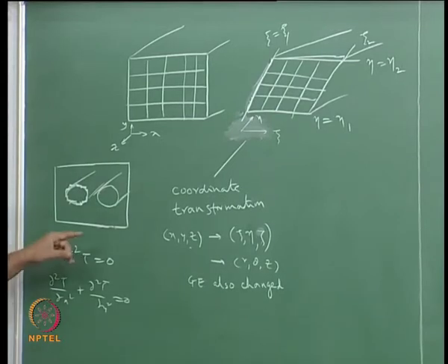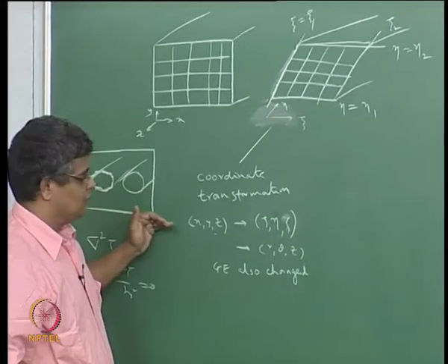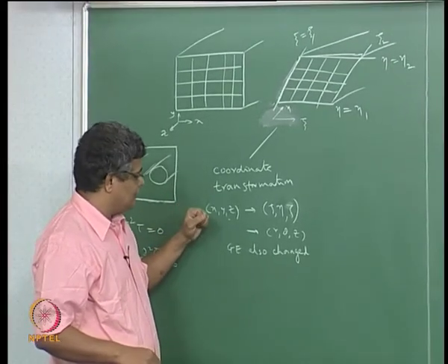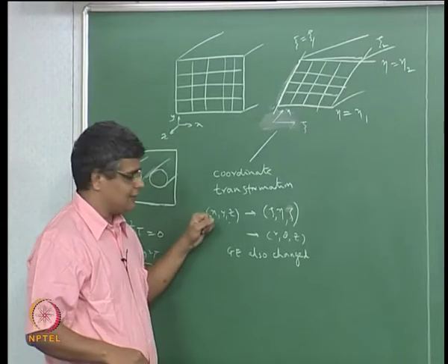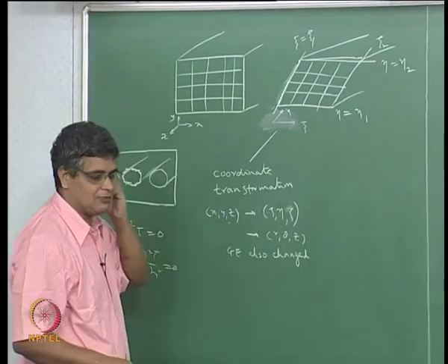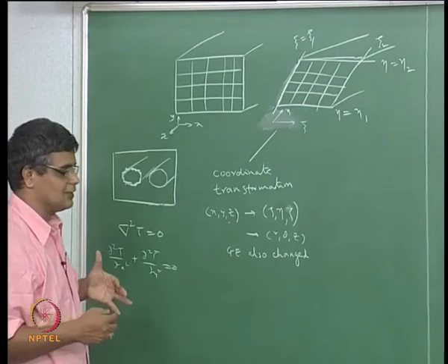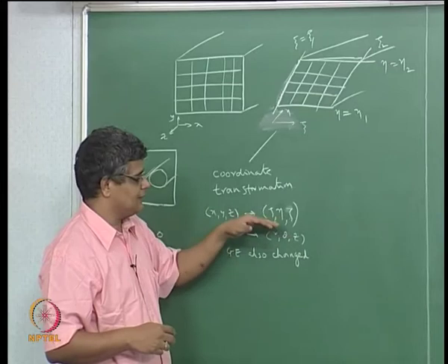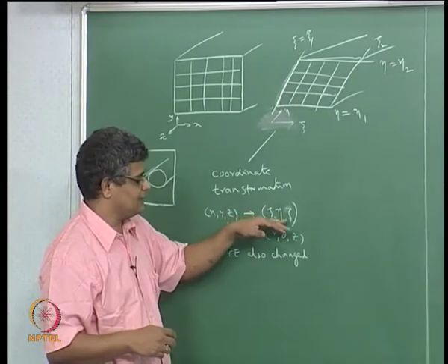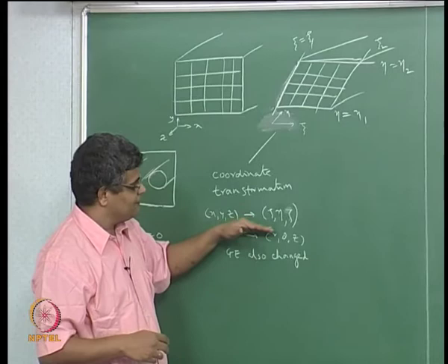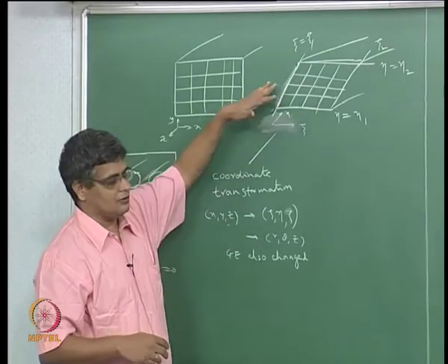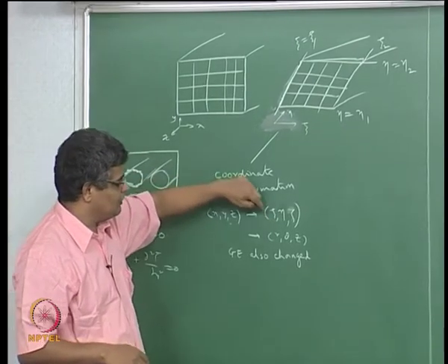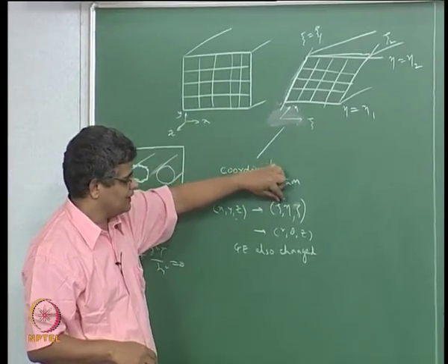So one approach is to move away from the restriction of xyz or r theta z or r theta phi type of transformed coordinate frames that we are very familiar with, into an arbitrarily defined coordinate system psi eta zeta, such that the bounding surfaces on which we want to apply the boundary conditions will lie along lines of constant psi, eta and zeta.